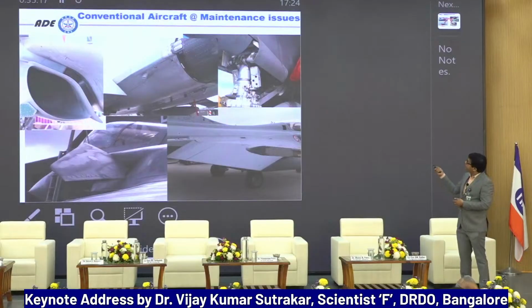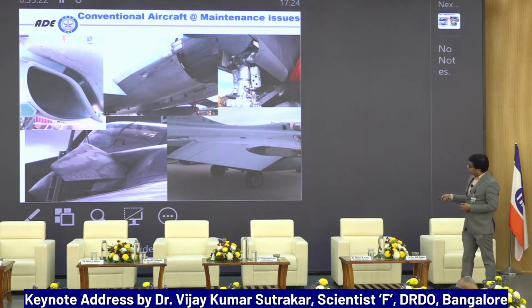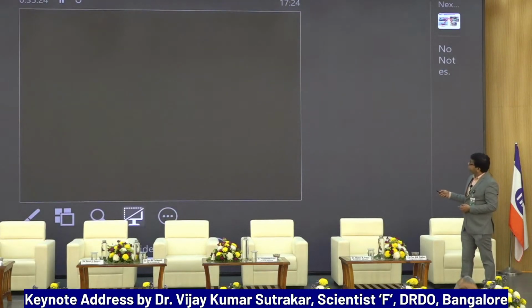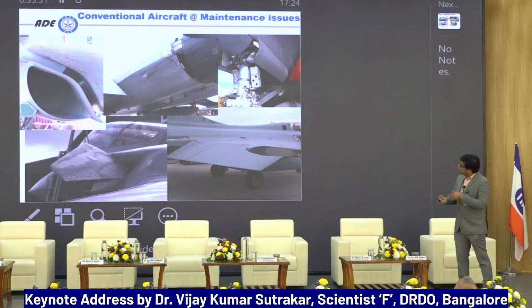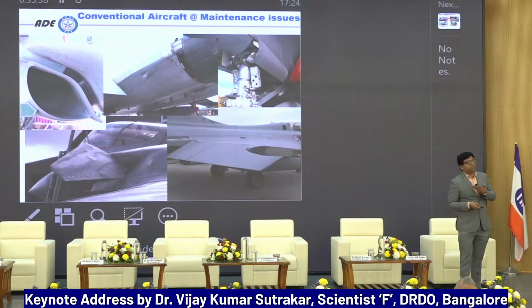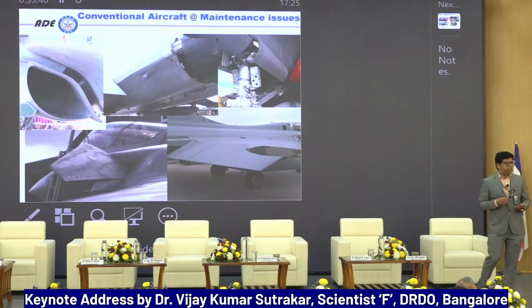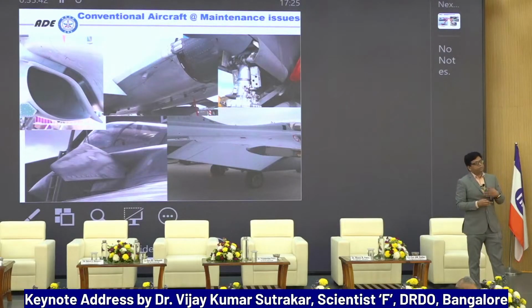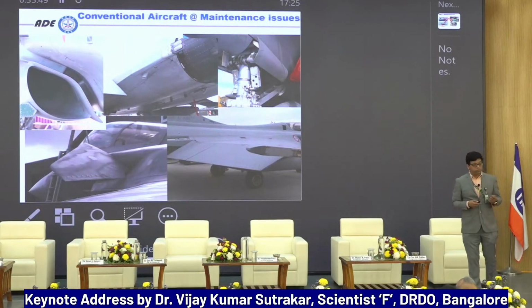So here I have taken a few images of some aircraft from the open literature where those serrations have been done, but you can see there is a lot of chipping off and discontinuities and other things. So it is always better, when you are doing an ab initio design, to use all these concepts in the beginning of the program. Later on adding something may not be a fruitful thing. It may be more problematic in terms of maintaining those birds.